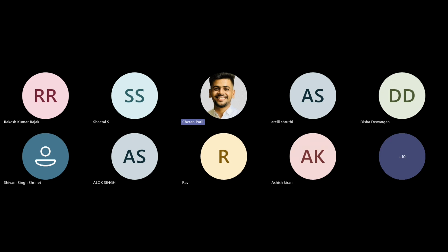Okay. So yeah, Amit, how to overcome the over constraint error report. Whenever you do the redundancy analysis, if I go to the redundancy analysis over here and click on the generate option, it will automatically highlight some regions in yellow. If it shows yellow, you can directly change the type. If it is showing redundant faces or redundant directions, you can change it from free to fixed. If you free or fix some directions of your joint, the type of the joint might get changed over here.